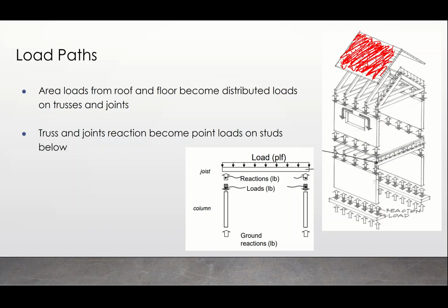Yes, the members itself can, but it's then going to these joists here, this pitched framework. So all of this area load needs to be divided between 1, 2, 3, 4, 5 different joists, and each one of those is going to get its own little distributed load on top of there based off of what it was holding from that area load. So every joist is going to be given a little portion of that, and then it moves on to the next thing. Okay, we got that.